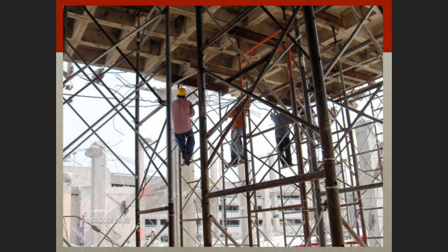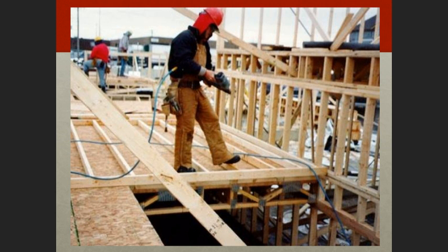So in this particular photograph, we see two individuals. There looks like three there, and they're working at a height, and they just climbed up on the structure there, and they're doing their work with no fall protection. Okay, so these employees are facing a significant hazard there. Here we have a construction worker with an obvious potential to fall more than 6 feet, and that would be the hazard there. And this is so common it's not even funny, but I just wanted to show you this photograph to point that out, that this individual employee should have some kind of fall protection, like probably restraint would work best.